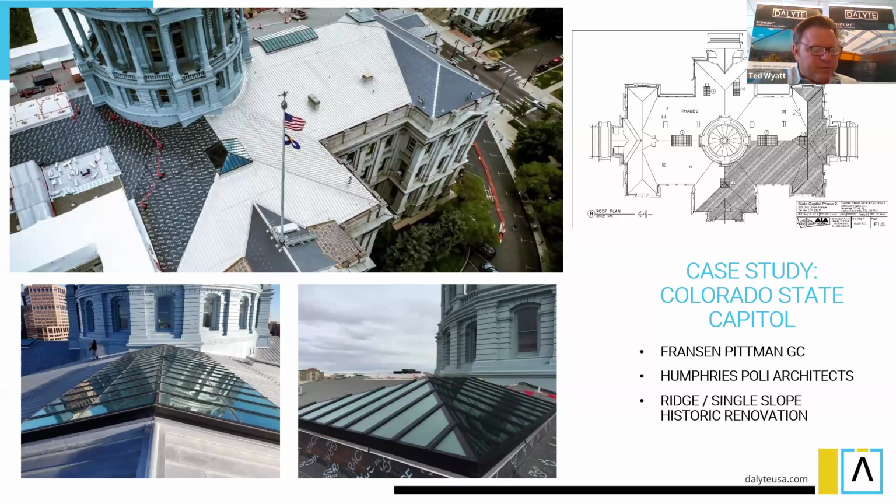But since it was a historic building, we had to duplicate the look of the old steel frame, which had narrow bays and a lot of divisions. So you see a lot of divisions and some false horizontal purlins to give that small bay look, which they originally had, to meet the historic requirements.